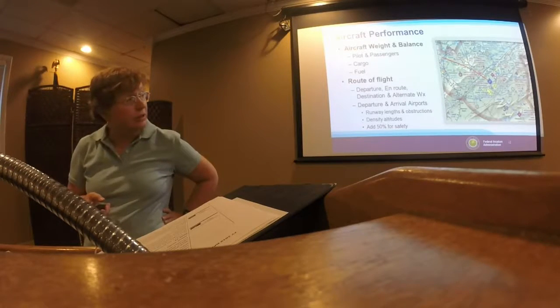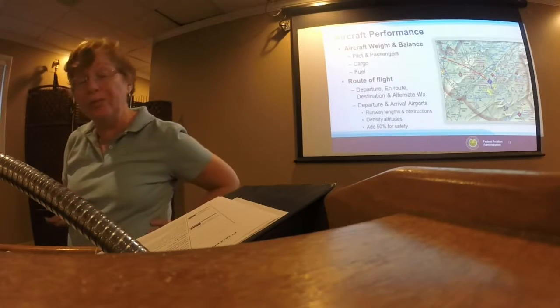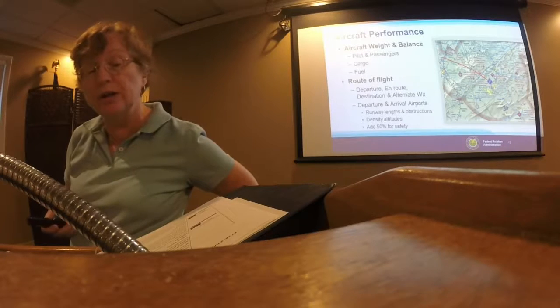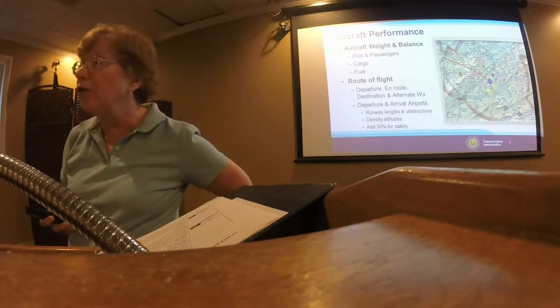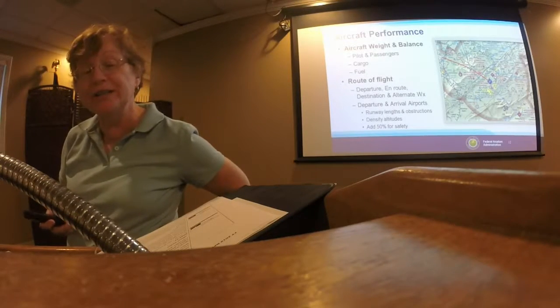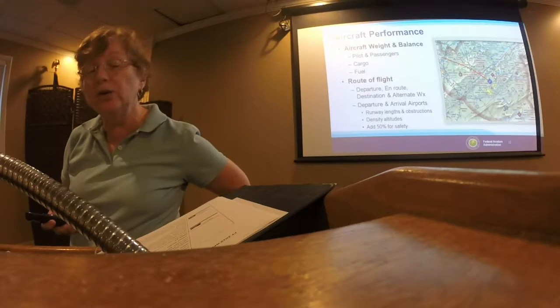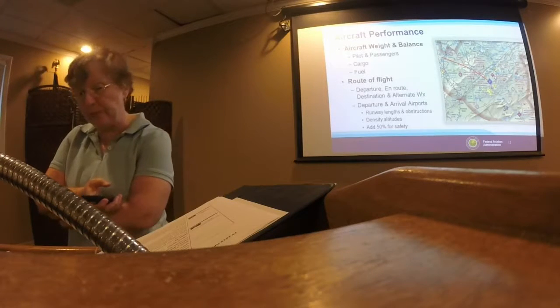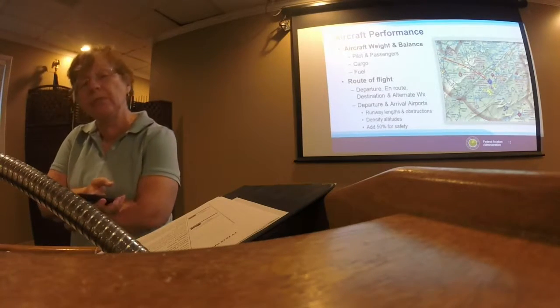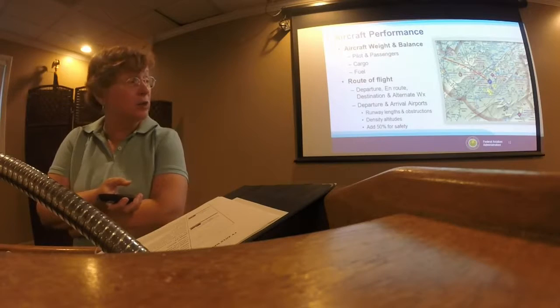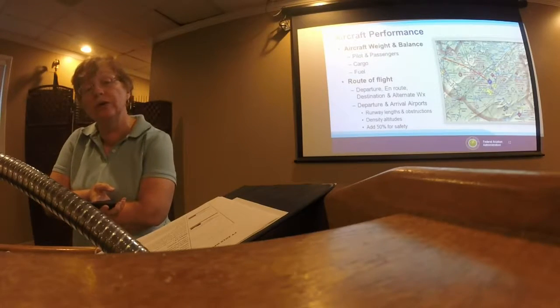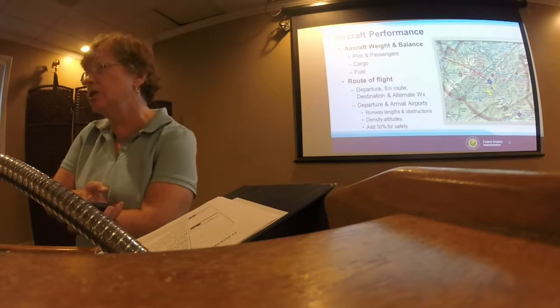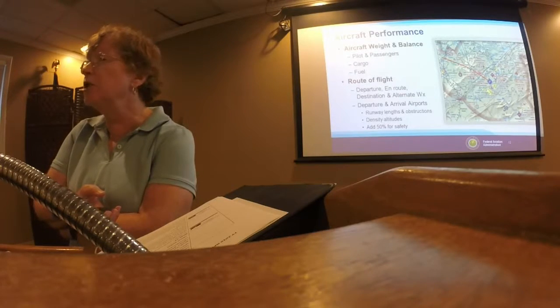And the closer you can get to the POH performance figures, well, the better you will be, but you need to be conservative when you calculate your performance and consider adding a safety factor. Some pilots add as much as 50% to the takeoff and landing calculations to give themselves a buffer.